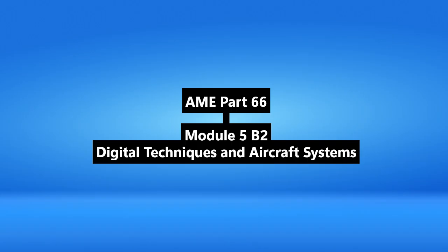What about the newer stuff? Aircraft networks, Ethernet, ARINC 664. Yeah, that's the evolution. Moving towards full duplex, sending and receiving at the same time, like a phone call, and leveraging standard networking tech like Ethernet, but with critical enhancements for aviation. Enhancements like? Determinism, guaranteed delivery times, guaranteed bandwidth. That's what ARINC 664 AFDX, Avionics Full Duplex Switched Ethernet, provides.